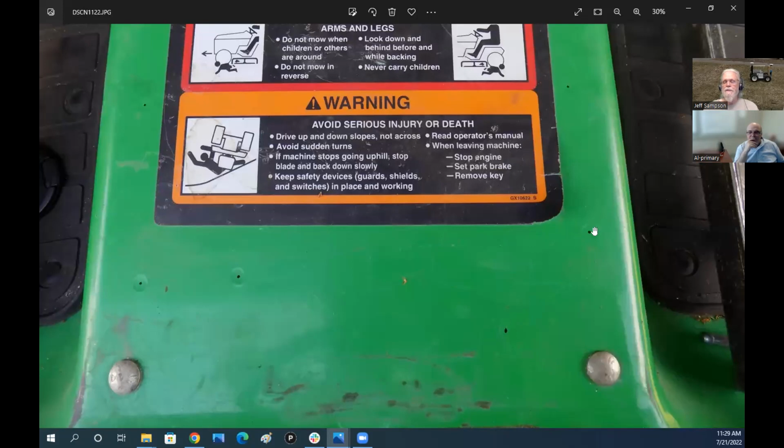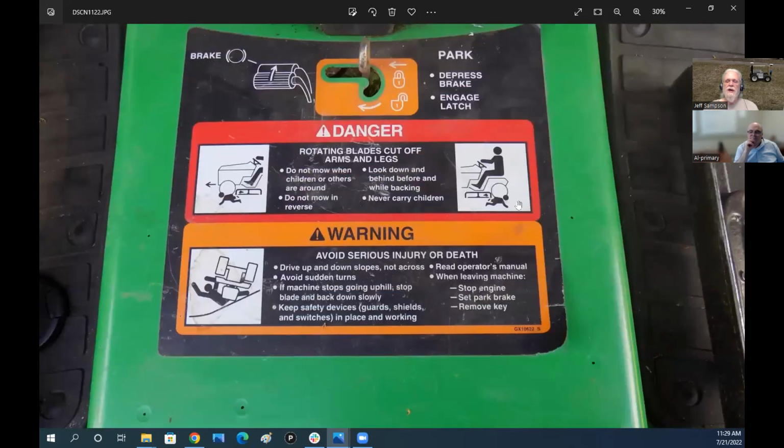For some reason, they found it easier to spot weld it there, and then the frame rail still runs right up through here, I think. And then here's another one. This is real close to where I want to drill. I decided right across here is where the front of my angle iron would go, which means the holes would have to go right about here. You can see this spot weld and this spot weld, and if I flip it over, I can see those on the back, so I can tell where those are. So if I put a hole right about there and a hole right about there, I think that will hit the center of my frame rails and make that work.